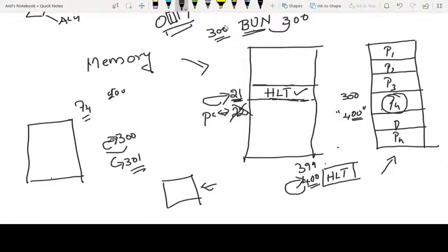Okay, so how to have the computer system halted? I should stop streaming the instructions. I should stop the stream of the instructions from execution. How can I stop it? There has to be a point at which the computer system has to be halted. That point is an instruction. For that I use a jump instruction, jump to the same location again and again and again and again. When it happens, the control will not go to the next location.